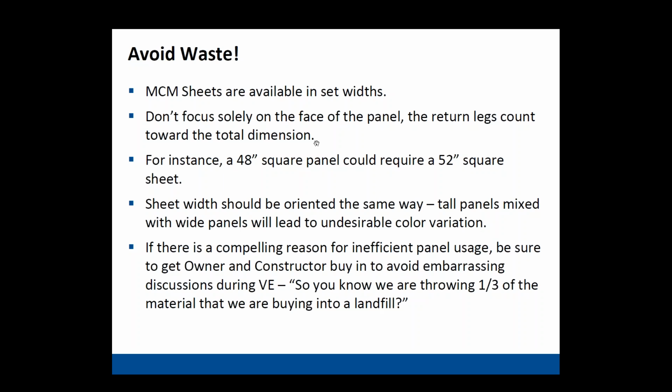You should always orient your sheets in the same direction. Sometimes somebody will say, oh, I want to mix and match tall sheets with wide sheets. That's going to get you in trouble. Even on the solid colors, the way that the coil coating happens, you can get a certain way that the paint will lay, and you will get checkerboarding. It's especially an issue with micas and metallics, but I wouldn't bet my life on the solid colors either. It'll be less of an issue, but still, you won't be happy.